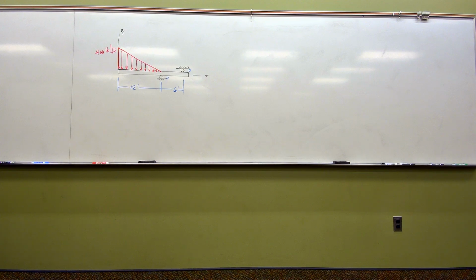So again, recalling what we did back on Monday, we had that rectangular version. We figured out what the equivalent load of that one was, which I remember was like 1,875 pounds. And that single arrow went through the centroid of the rectangle. Then we figured out 500 pounds for the triangle, and that one passed through the centroid of the triangle.